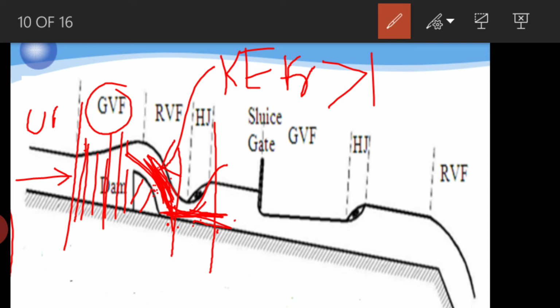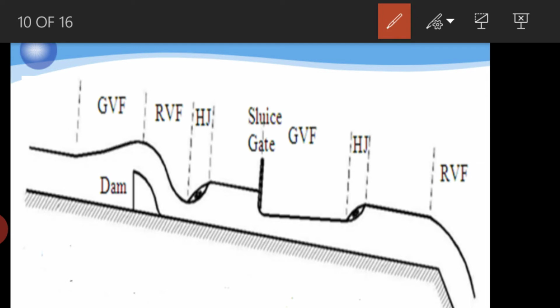So earlier, at the lower depth of flow, the kinetic energy was very high. The moment it comes in contact with the flatter slope, suddenly the depth of water increases, and suddenly the energy is reduced. That condition is what you call a hydraulic jump. You can look here. So the hydraulic jump, the moment it comes, suddenly it jumps like this, and here the depth of flow is very high, and the depth of flow is very less here. That's why it is given here